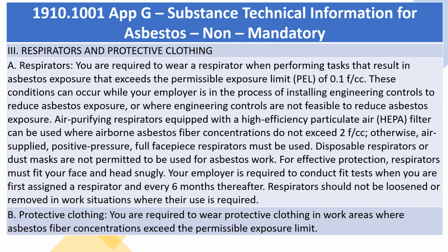Air purifying respirators equipped with a high-efficiency particulate air (HEPA) filter can be used where airborne asbestos fiber concentrations do not exceed 2 f/cc. Otherwise, air-supplied, positive pressure, full face-piece respirators must be used. Disposable respirators or dust masks are not permitted to be used for asbestos work.